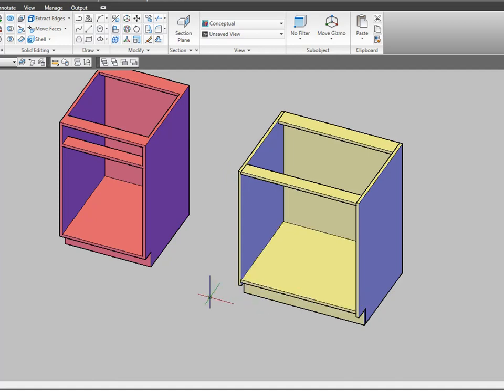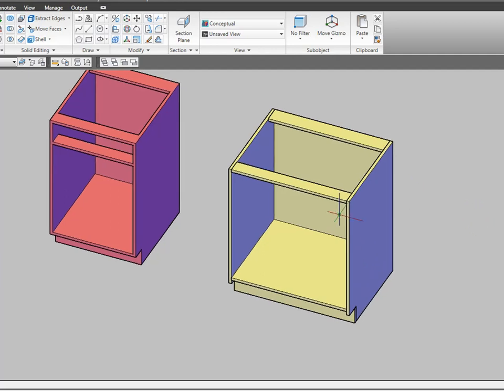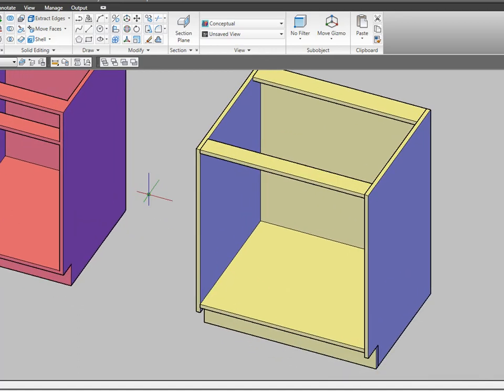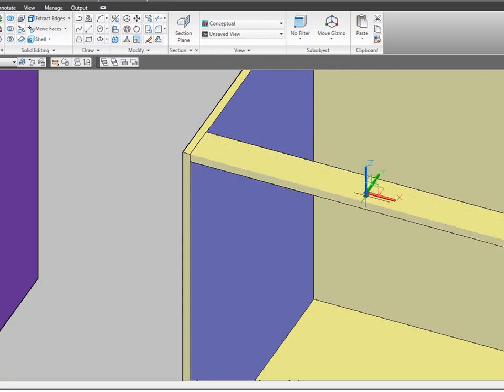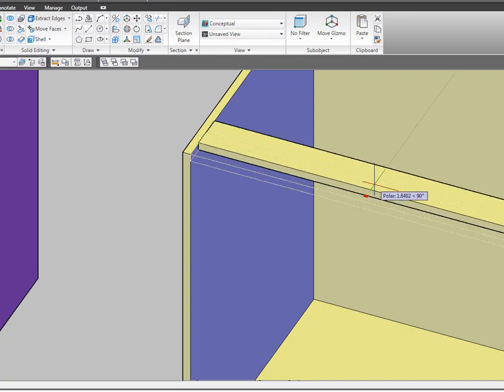Well, actually, before I do that, let's adjust the depth too. Because we're going with a 3/4 inch face frame, right now we're at 24 inches of cabinet depth, and we need to knock that down, assuming that, you know, there are different construction methods, of course. I'm assuming that we're just going to drop it right on, so I'm going to take 3/4 of an inch off the depth of the cabinet, and just push this back